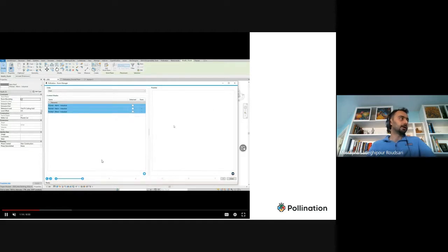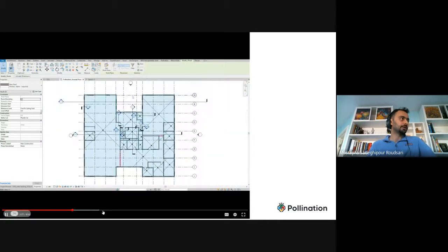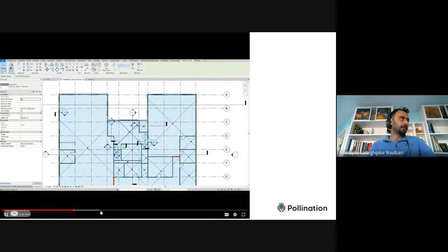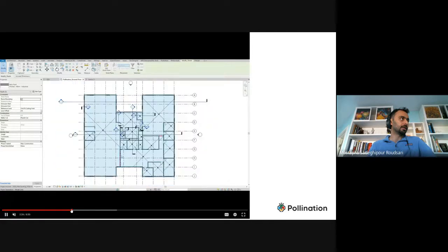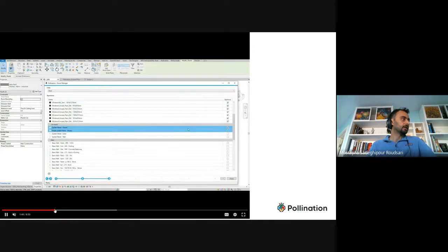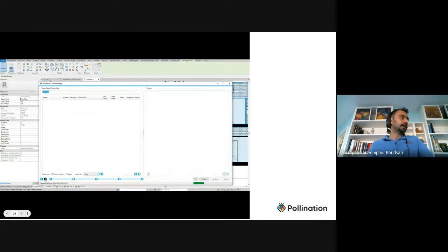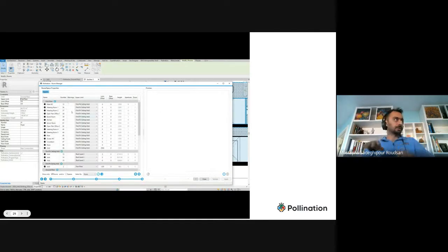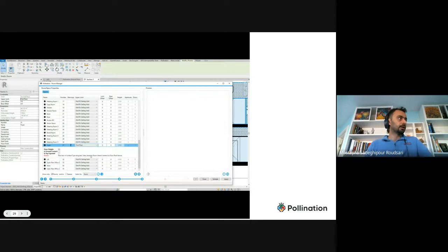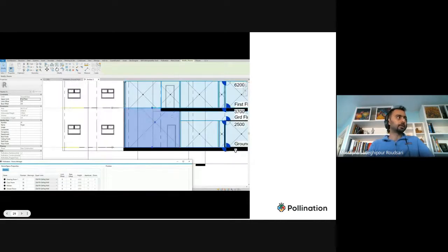So basically, I go to selecting the aperture, and here adding the context for the roof, selecting all the apertures. And then, blah, blah, blah. Like this one that you see here, because the room is double height in one place and not on the other side, how do you resolve that? That's another new thing that we have added to the Revit plugin: even in detailed mode, you can right-click on a room and override the height. So if you have a room that is multiple height, or something is not right and you want to fix it, you can just right-click on it and overwrite the height.